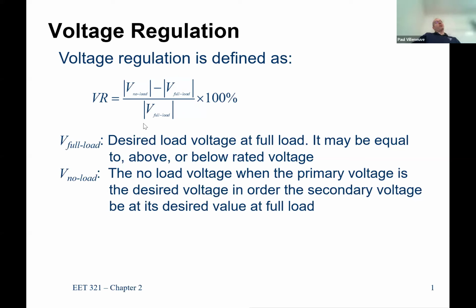The reason is that when you have a transformer that's fully loaded, or nominally loaded, and then something happens to the load and it trips offline, we want to see what that secondary voltage floats to as the load is instantaneously removed. That's the no load condition. Here is my source, which is owned by the utility, and there's a bunch of load there. They've adjusted that voltage so that the voltage over here is approximately nominal.